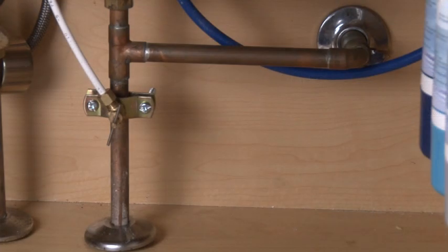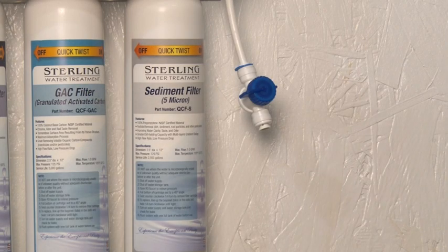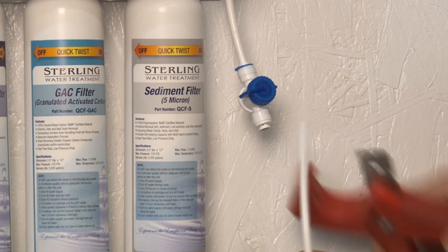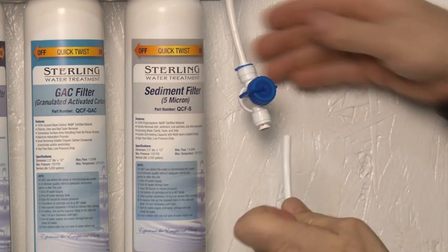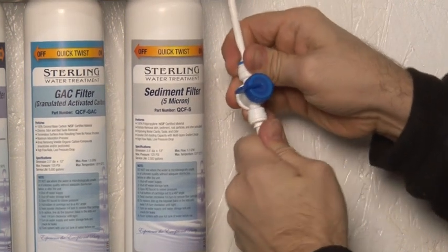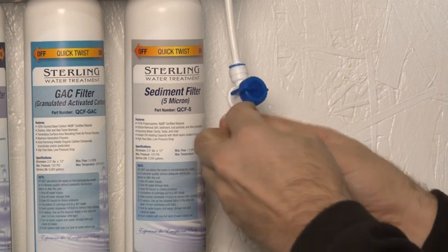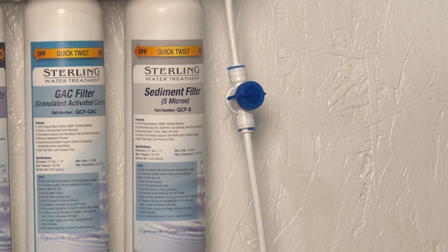A self-piercing saddle valve or T must be installed to provide feed water to the QCRO system. A 1/4-inch supply line should be run to the manual shutoff valve on the inlet of the QCRO. It's very important to squarely cut the end of the tubing and fully insert the tubing into all fittings. The tubing must not only pass the stainless steel grippers, but must also extend beyond the O-ring, which is deep inside each push-in fitting. A seal is not made until the tubing passes this O-ring.